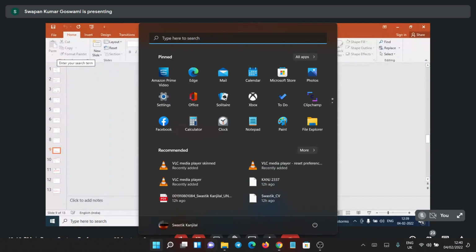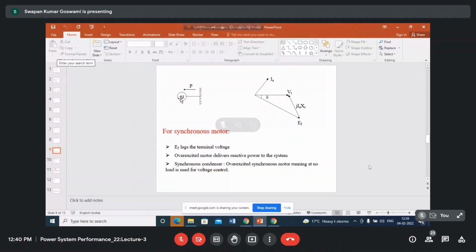We shall be discussing something regarding the synchronous motor also, because we shall be discussing the frequency control and voltage control. You see that synchronous generator basically is a generator where the field current is DC and armature obviously is AC. In synchronous motor also, field current is DC, and the operating principle of synchronous generator and motor obviously will be the same. Okay, there will be field current delivered from DC, and there will be armature which is AC.